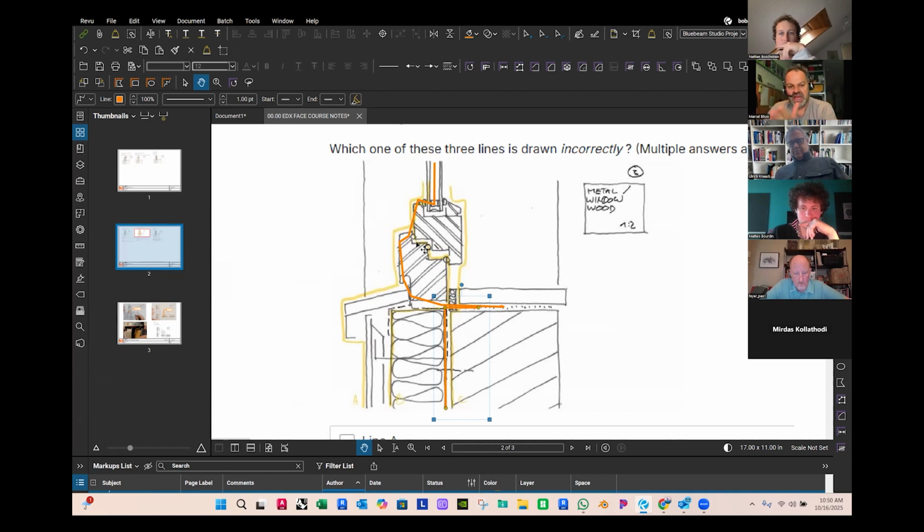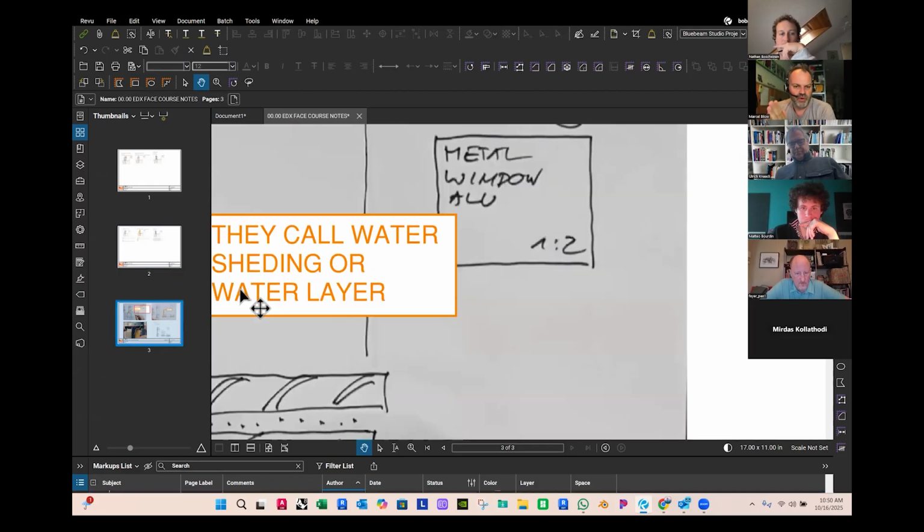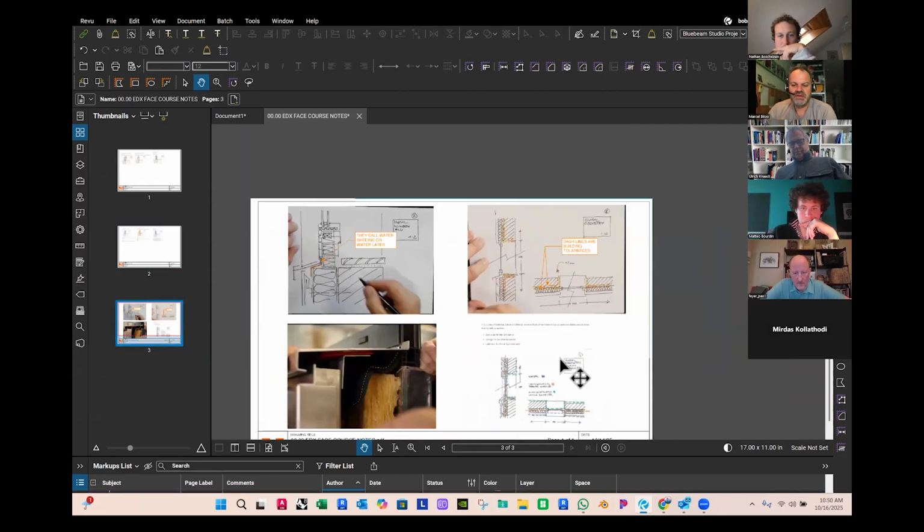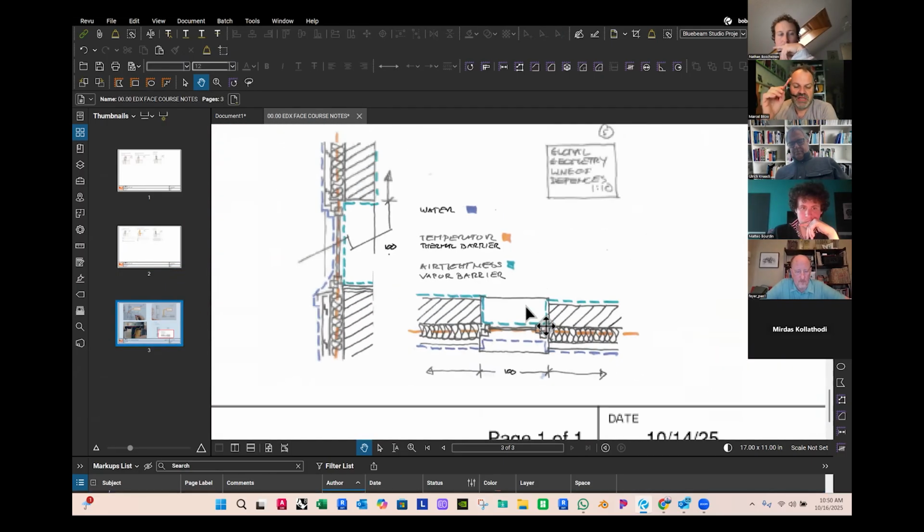But the inner airtight layer or vapor open layer is what we assume most likely to the inside of the window profile, covering the little insulation that gaps the wood profile with the masonry or the load-bearing structure underneath, and then into a little bit of the window sill.